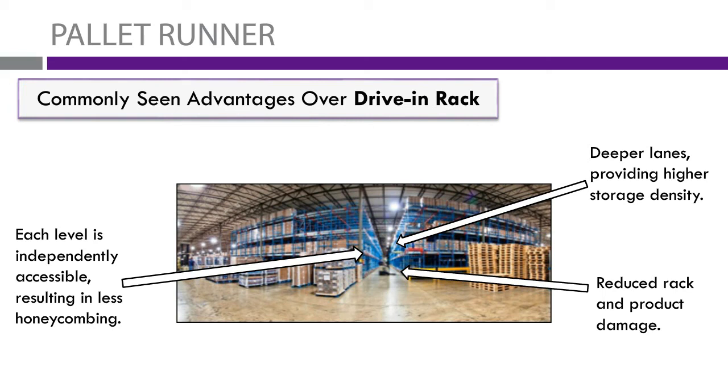So when you're looking at how deep your system is, yes, we can make a drive-in rack pretty much as deep as you'd like, but the deeper you go, as I mentioned, the farther your driver will have to enter the system, more likelihood of damage, and obviously the deeper that damage happens, the much harder it is to get in there and repair that. Pallet runners, they can pretty much go as deep as you need. I believe the largest Pallet Runner system out there right now goes about 83 pallet positions deep. So the depth isn't an issue, and it's all the machine doing the legwork. Your driver doesn't have to enter the system.